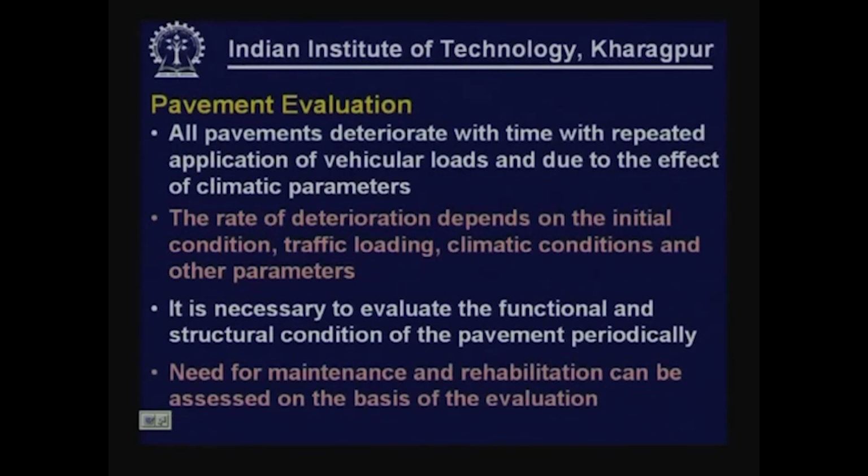In fact, the rate of deterioration would depend, if you recollect the AASHTO equations, either for concrete pavement or for flexible pavement, you can see the number of load repetitions a pavement can satisfactorily serve is a function of various parameters, pavement related, reliability related, structure related and various other factors. So, to properly explain the performance of a pavement, how long it is going to last, what is going to be the condition of the pavement after certain number of years at a given point of time, if it starts with an initial condition, it requires a lot of inputs.